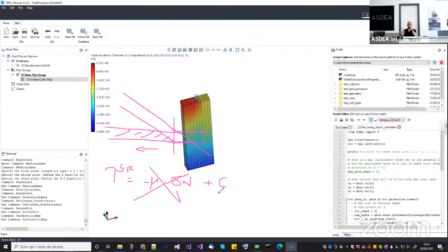But in my opinion, you should not use it, because the cohesion makes sense only if you have your pile here, then you have your soil here, and here you have some kind of cohesion element that has a cohesion. But actually, if you want to simulate a non-perfect contact surface, that can be useful too. But yes, if you want to switch friction on and off, you will switch this one on and off, I think.